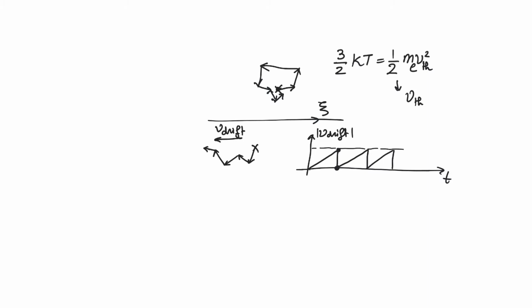Why does it accelerate? It accelerates because it lies in an electric field. The electric field imposes a force upon the electron, and the force will cause it to accelerate. This is Newton's law. So it will accelerate. If it were in vacuum, it would keep accelerating forever. It is not in vacuum, so it will collide. Actually, it normally collides with an impurity atom, because it is the irregularity in the crystal that we have, and it comes to a complete stop.